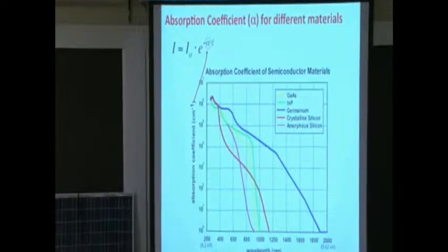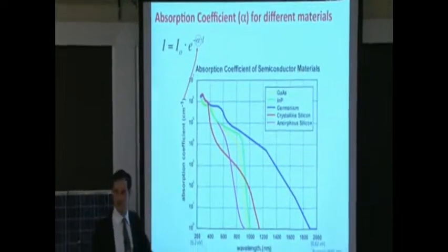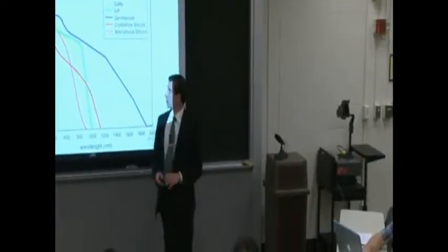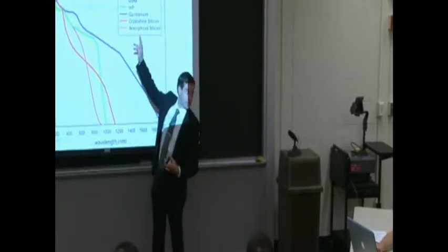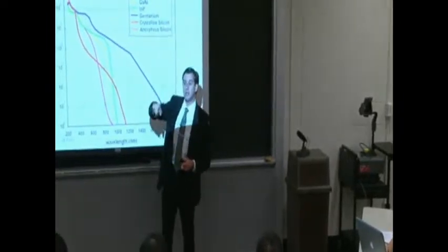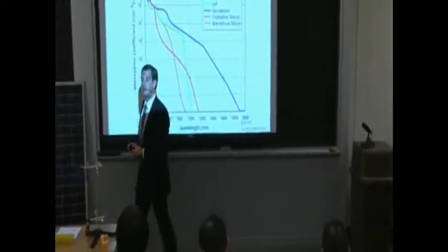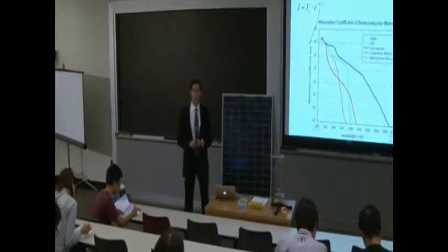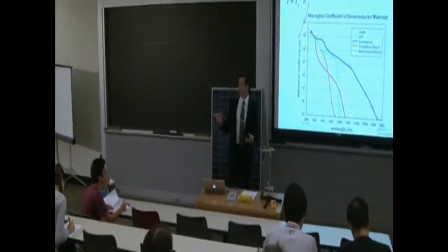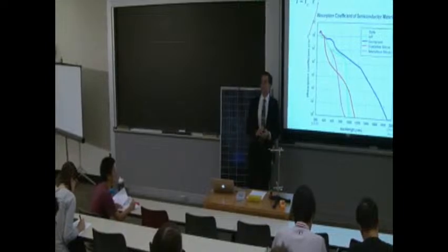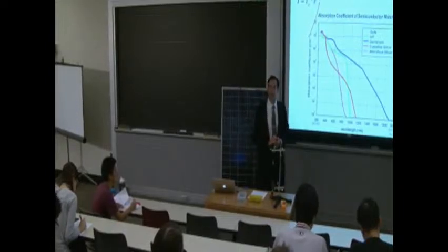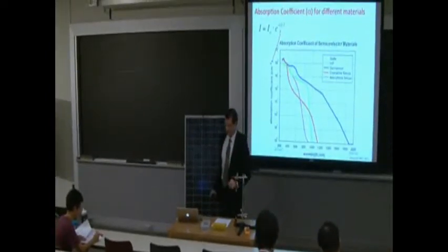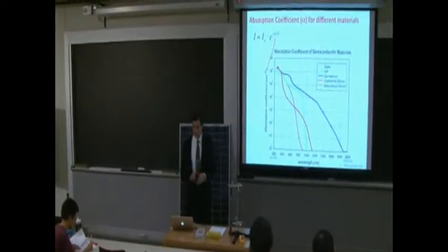And so the L's that you obtained, let's go for gallium arsenide first. Did anybody manage to walk all the way through that calculation? 20 micrometers. 20 micrometers for our gallium arsenide or for our silicon? Gallium arsenide. Did anybody get any other numbers for gallium arsenide? 0.4 microns? Yeah? That's sounding more in the ballpark. Anybody else? 23 as well. I would have guessed that the number would be rather small for gallium arsenide, something in the range of, say, a micron in that order.